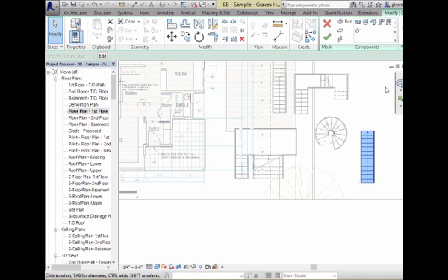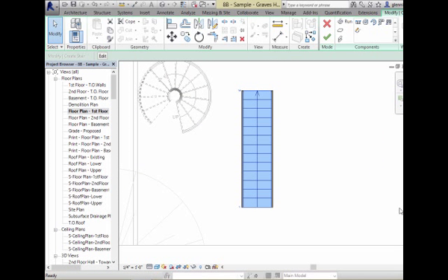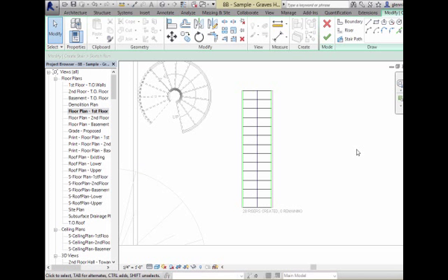What happens is, if you want to, you can go through and actually convert a stair into a sketch, and that gives you even more detailed control. So you can edit the sketch of a stair. It'll actually show you there's a run line, there's boundary lines, there's riser lines. So if you had a very custom situation, you probably won't have this unless you're really trying to accomplish something very architecturally different. I could, for example, change the boundary line. So I could go ahead and pull that on out.